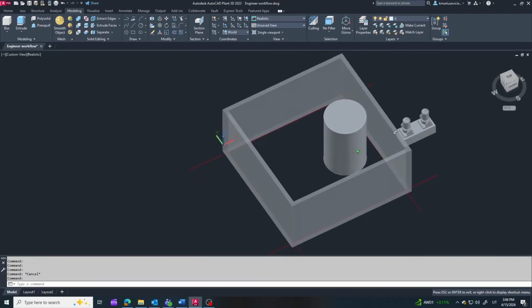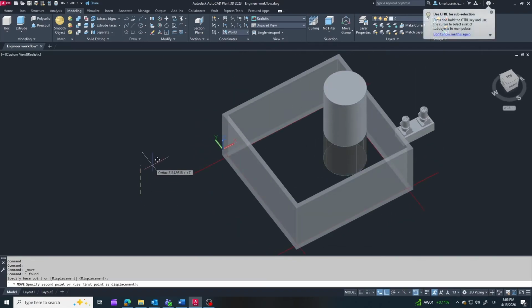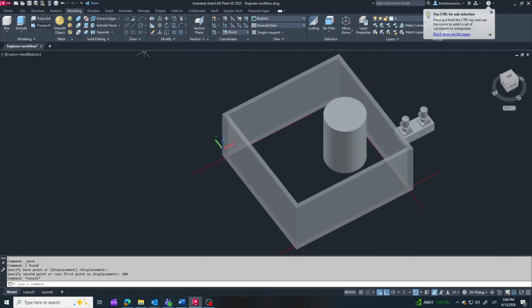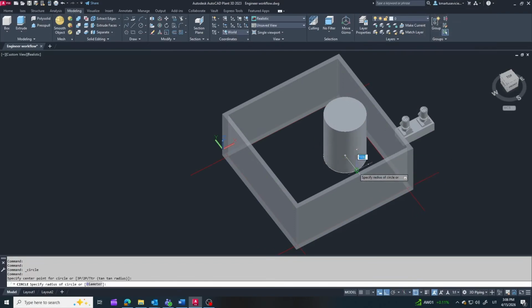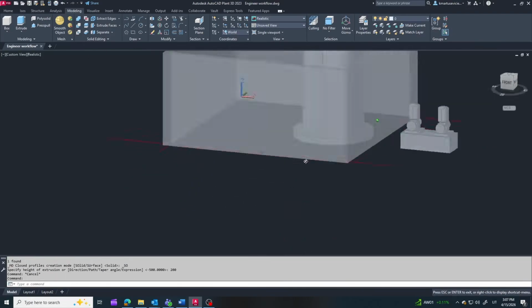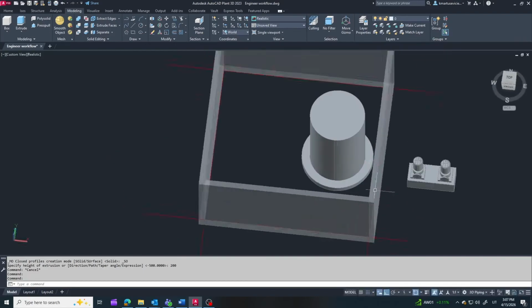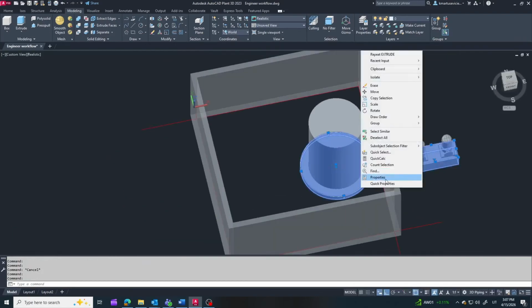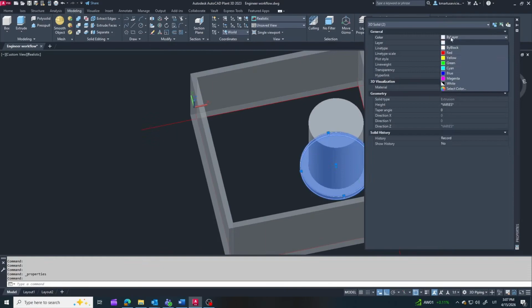Our tank is also standing on the ground. Sometimes, we can place it directly as it is, but in many cases, it's better to add a foundation. For example, a circular concrete base, about 200 millimeters high and around 200 millimeters wider than the tank diameter. This gives better stability, cleaner installation, and improves drainage around the tank.